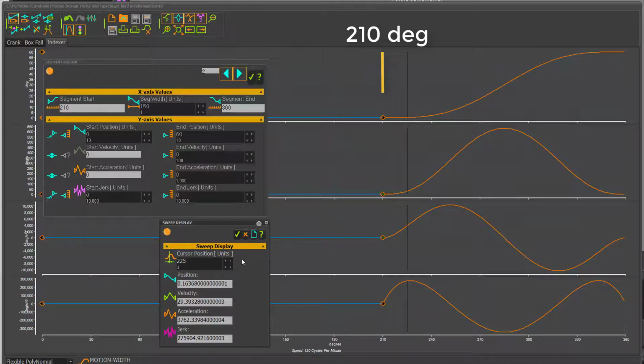And if we're working with a packaging machine, I think tolerances of 0.163 of a degree, well, obviously it depends on the radius of the turret, but I know the radius of the turret is 100 millimeters, that would correspond to a very, very small displacement in millimeters. So what this means is that we can lengthen the segment without any serious penalties. Because if we lengthen the segment, then we reduce the accelerations. So we're gaining the advantage. We can keep the acceleration roughly the same, but we can make a much, much smoother motion.